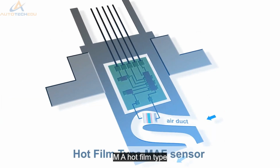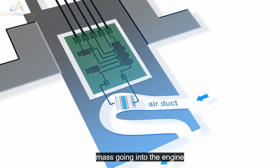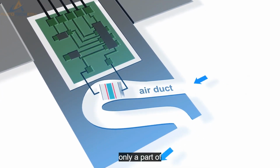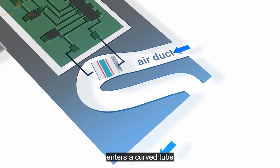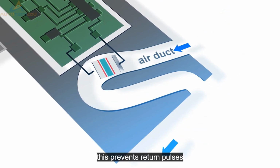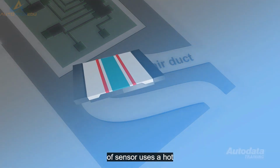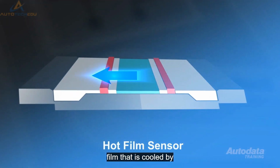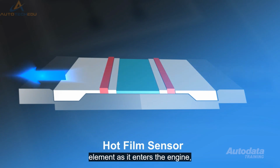A hot film type MAF sensor measures the air mass going into the engine. Only a part of the air is measured. The air to be measured enters a curved tube. This prevents return pulses being measured. This type of sensor uses a hot film that is cooled by air flowing past the sensing element as it enters the engine.